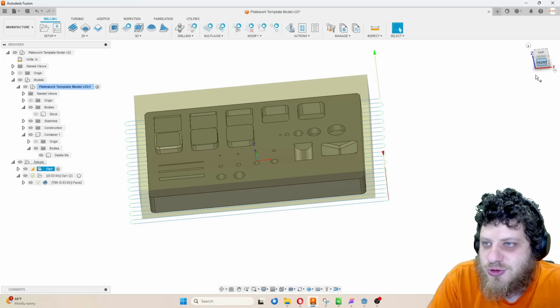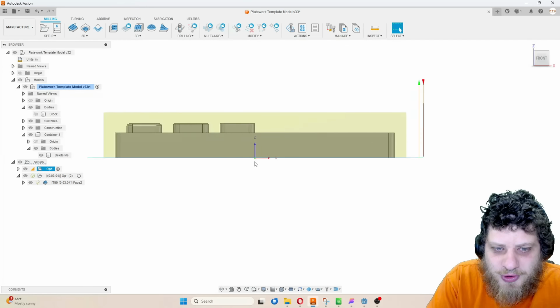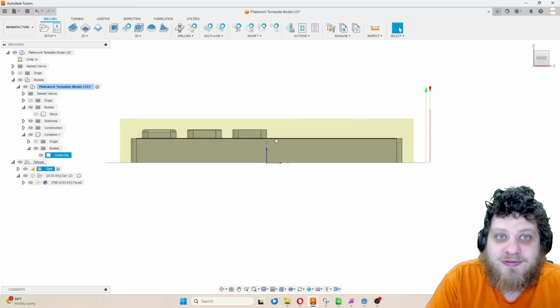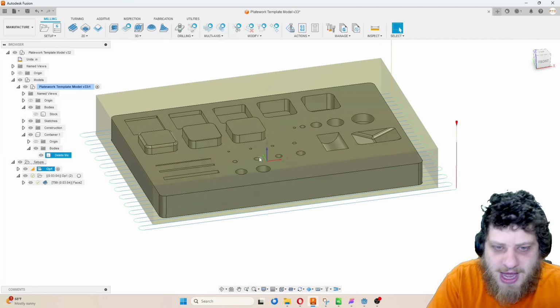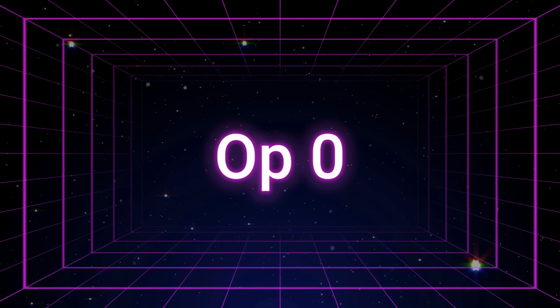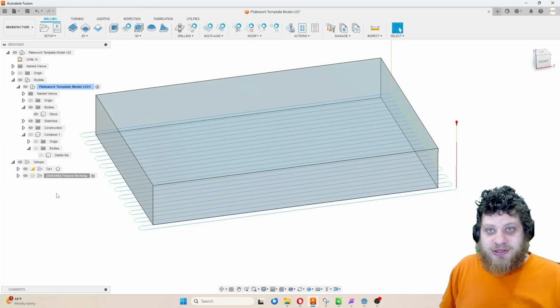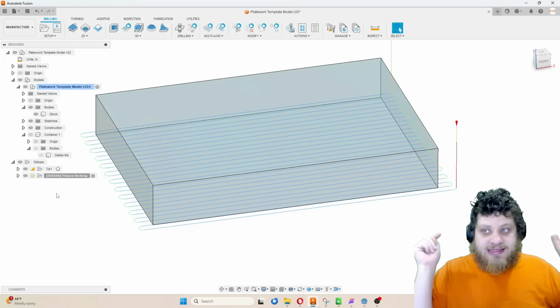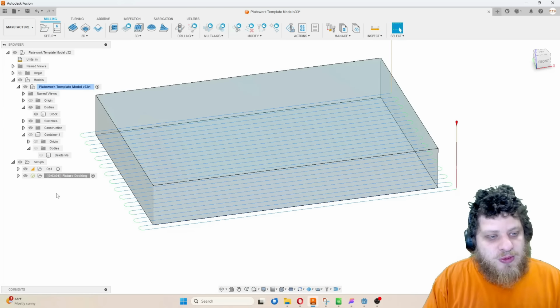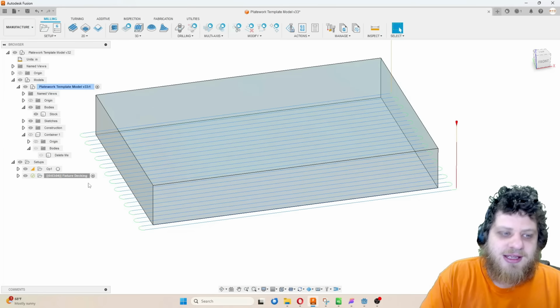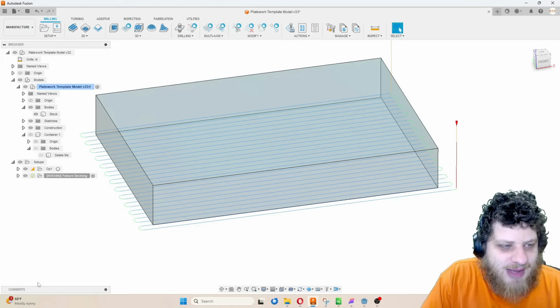And because this tool path is directly on our work coordinate system, we'll know that that surface of the fixture is right where we want the bottom of our part. So remember when I said that most of the time when I do this, I face off the bottom of my material before I get started? We need that operation now. And it's actually almost identical to this fixture decking, but with a couple little mild changes.